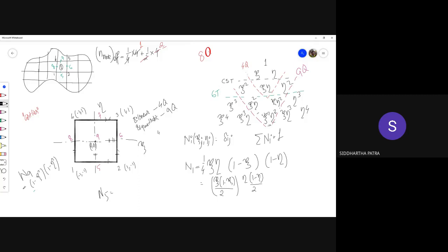Because 8 is twice of 4, but that is not the fact here. If you do a really large mesh, because each of the mid-side nodes is only shared between 2 elements, the node count doesn't increase by twice, it actually increases by thrice. This is the quantity that I'm writing, number of nodes per element.